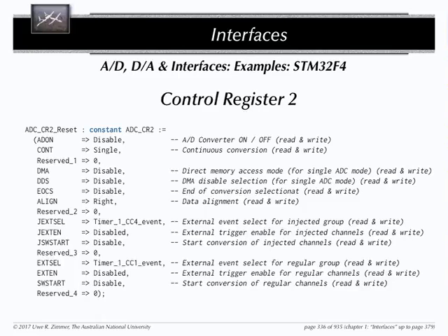And as you can calculate the time which this will take based on the clock of this thing and the value which is set under, these things are then called timers, or sometimes referred to as hardware timers, as opposed to what you emulate in software in your programs. A hardware timer is something you set and forget, and then it does something for you at some point. Not necessarily for the CPU, can also trigger other parts of your system. So we have a CPU, different forms of memory, and a timer.